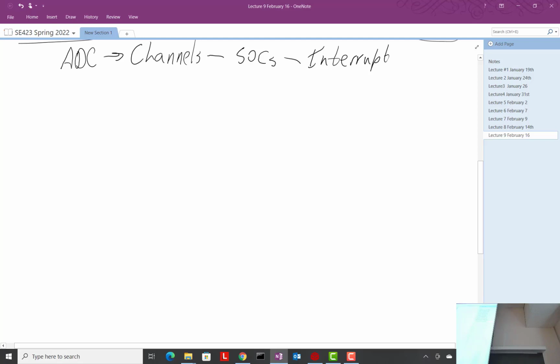With a DAC, depending on its resolution, we are going to be dealing with a 12-bit resolution DAC. With a 12-bit DAC, we have 2 to the 12th different voltages we can output, with 0 being the first one and 4095 being the maximum voltage we can output.